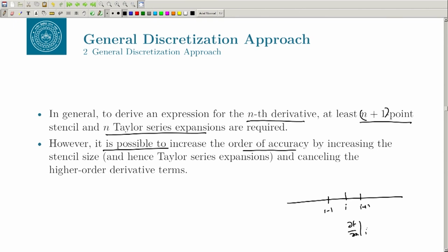This is the advantage of the finite difference, right, that basically you can use the stencil size as big as you want, okay, to get your gradients as best as you can. This you cannot do in finite volume. Okay. There these points are not well defined or not in order like I plus 1, I plus 2, I minus 1 and I minus 2 and so on and so forth, right. So, you cannot use this scheme.